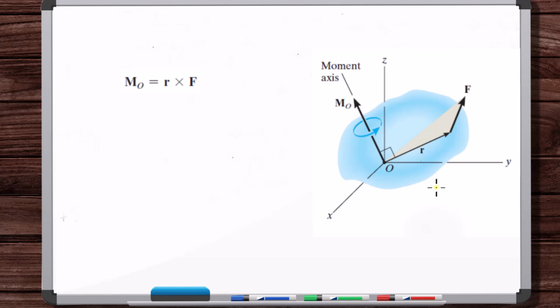Like, you know what I mean? If F was here, it's not that you have the same magnitude of moment but the position of the moment changes. No, the moment's tail is always at that point. Now, this is just for this specific context. But we're going to see that in most scenarios in statics, forces act as sliding vectors. In some circumstances they don't, but in most situations, forces are sliding vectors.